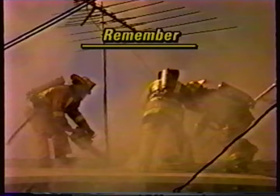Here are the key points you must know before attempting peak roof ventilation. Wear all protective clothing and SCBA. Always plan a second means of escape. Use a backup firefighter when using a power saw. Constantly monitor fire conditions and their effect on the roof decking and supports. Beware of sagging or spongy roofs.